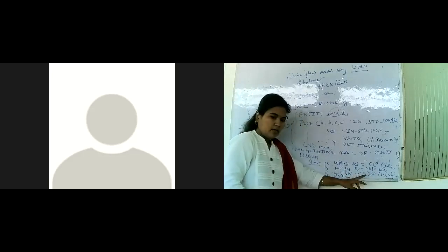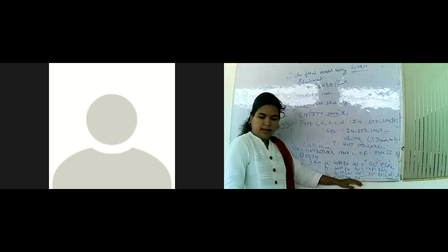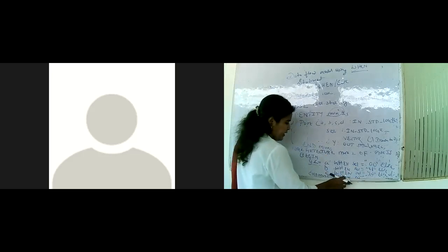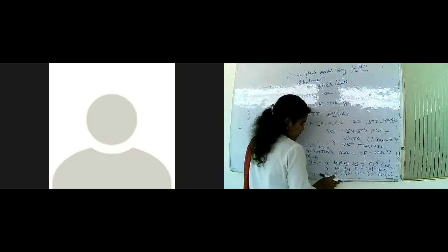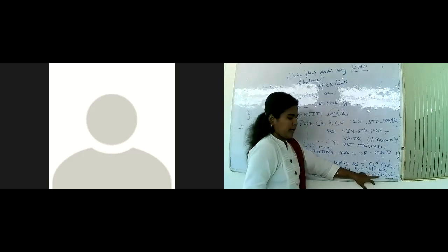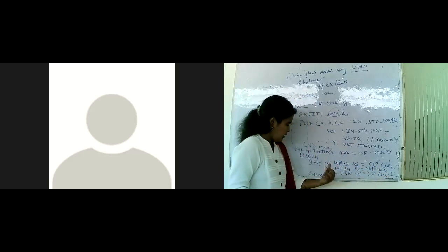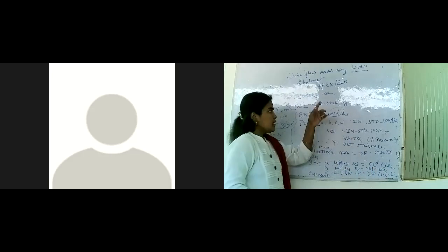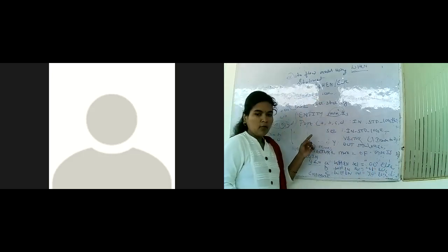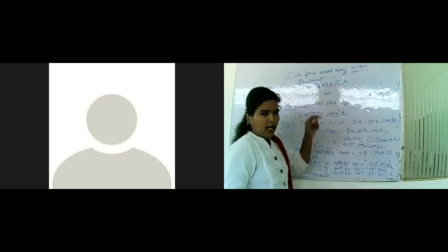Okay, you can write this also. Otherwise, directly you can write C when selection line is 1, 0, else it will be automatically D only, there is no other option. That is the end of the mux 2. This is the example of a multiplexer with the help of the when else statement.